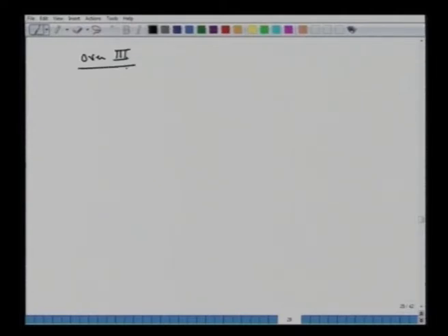Okay, so that's what we did when we developed our expressions for theta contact. So now we are talking of the last 3 and 4 region. Again, recall our discussion. Here we have the solid moving like this and air coming like this. For this, when we wrote down the energy balance, or the heat load, we said that we have to make certain approximations, certain iterations, so we have to assume certain surface temperature.